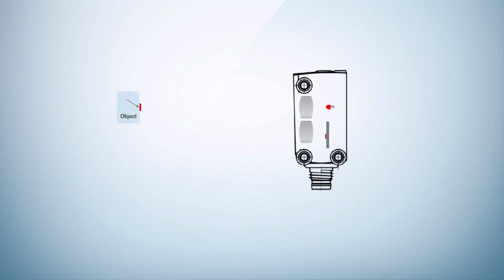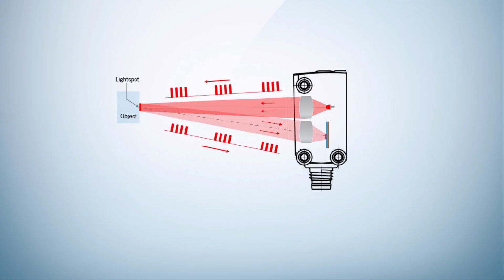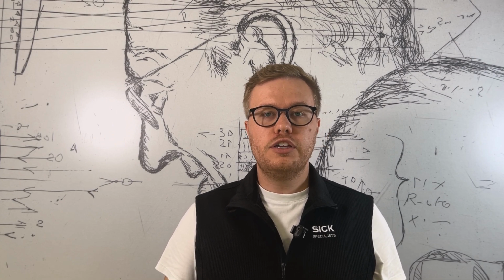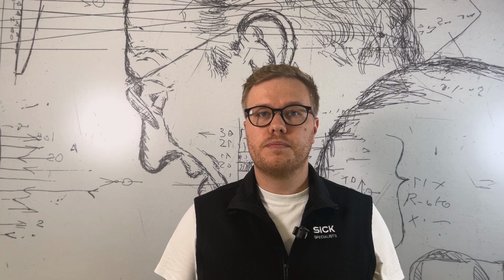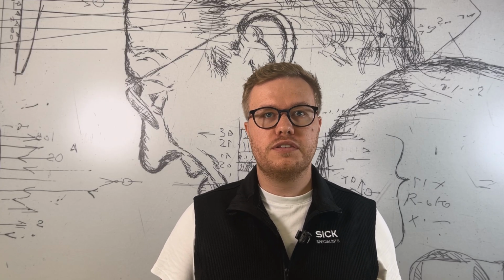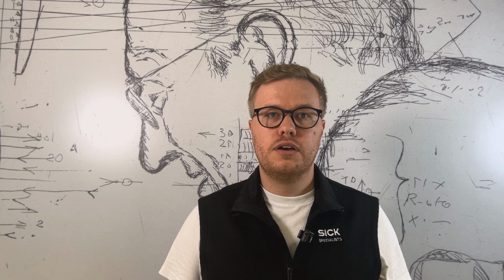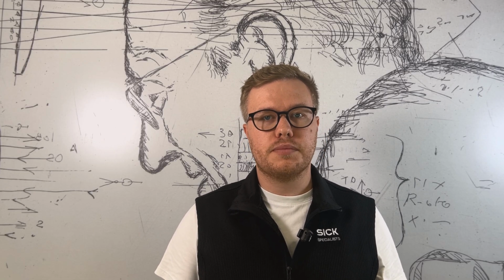In order to work reliably, the sensor must distinguish its own transmitted light from ambient light generated by LED lamps or camera system illuminations, for example. It achieves this by the ASIC sending out a sequence of packets of 4 transmitted pulses each. The ASIC filters these pulse patterns from the receiver's digital signal stream. In standard mode without ApplicationSelect, each pulse pattern is evaluated individually. In this mode, the sensor typically operates with a switching frequency of 1000 Hz and a response time of 0.5 milliseconds. Here, the intensity of the received signal plays a major role.